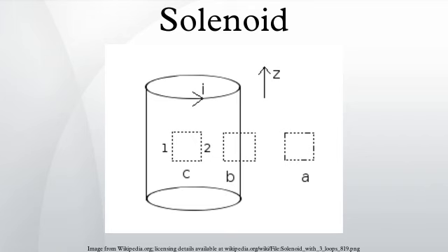The rotary solenoid has a similar appearance to a linear solenoid, except that the core is mounted in the center of a large flat disc, with 2 or 3 inclined grooves cut into the underside of the disc. These grooves align with slots on the solenoid body, with ball bearings in the grooves. When the solenoid is activated, the core is drawn into the coil, and the disc rotates on the ball bearings in the grooves as it moves towards the coil body. When power is removed, a spring on the disc rotates it back to its starting position, also pulling the core out of the coil.